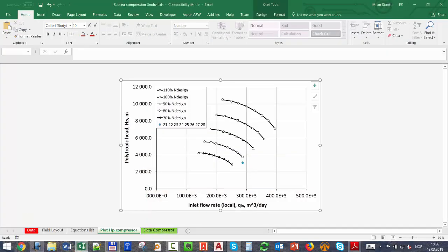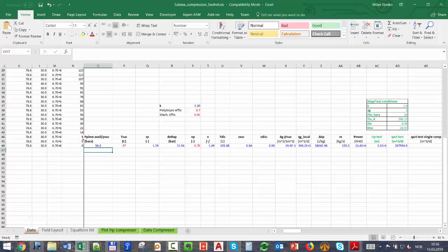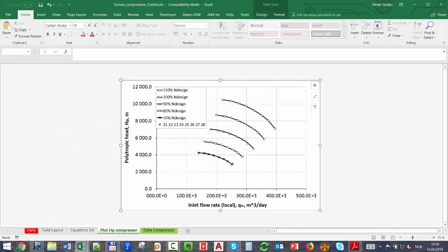So here instead of using, and again, you guys have to do it correctly. Here is T suction, and you have to put a T at the discharge of the cooler. You have to put another column with the discharge of the cooler. Here I'm just going to change that number, and I'm going to put 20. So the rate change, the polytropic head also change. Okay, victory looks like. It's barely inside on the line, but it's inside the map.